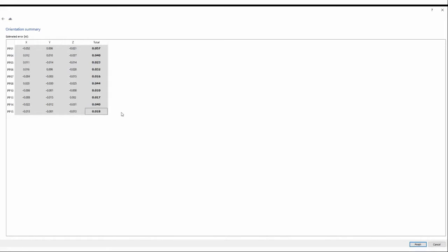Even without the ground control points, we can get good accuracy of generated results. Generally we will get better XY positioning than altitude. All of our tests show that in Z we can expect slightly larger offsets than in the XY direction.